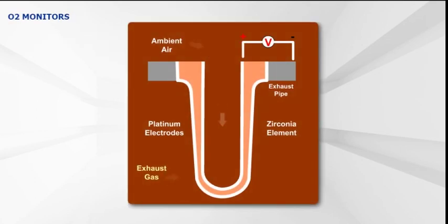Diagnosing a problem with closed-loop fuel control requires a technician to determine if the source of the trouble is electronic or mechanical. This typically is accomplished using artificial enrichment, propane, and enleanment, vacuum leak. However, with OBD II, the fuel control and O2 monitors can isolate the problem automatically. In this section, we'll focus on the operation of the O2 monitor and the O2 heater monitor.